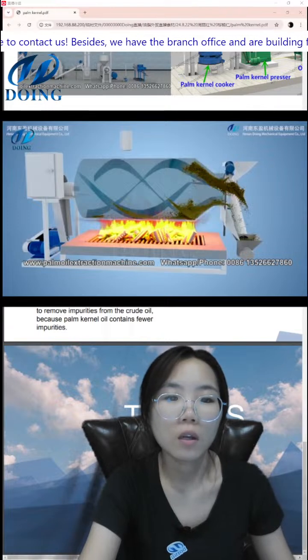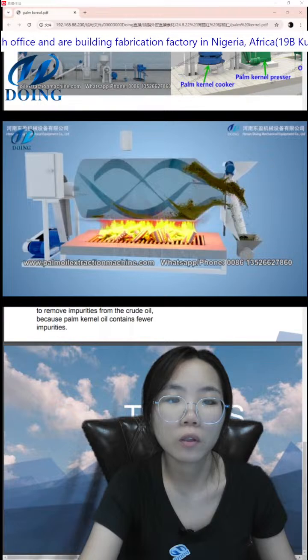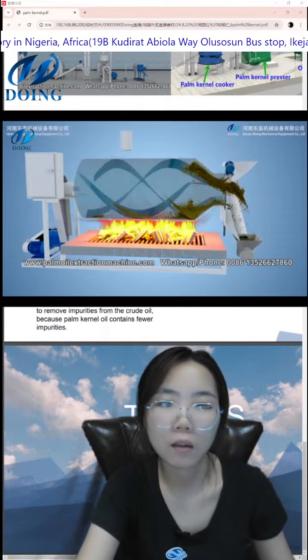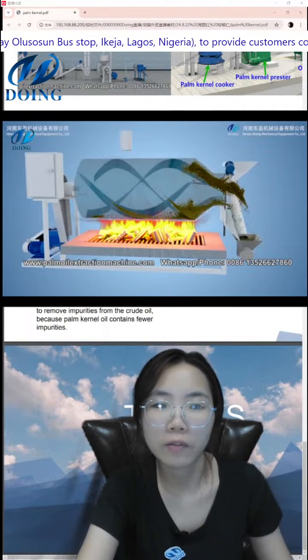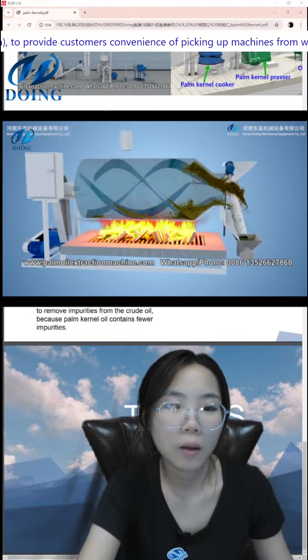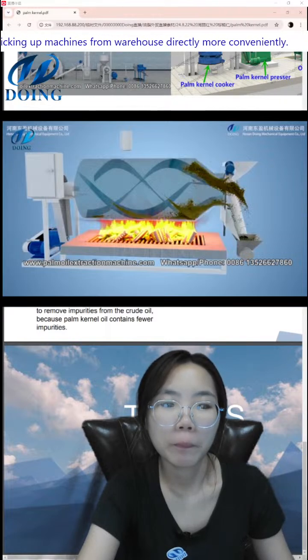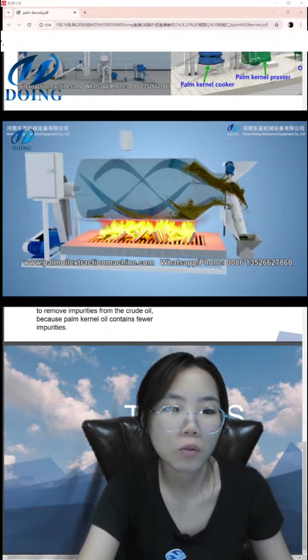For the roaster, the water level before entering the press needs to reach about 4% to achieve the best palm oil yield. And this cooker is the Bellman's cooker. After separation of the kernel and the shell, the shell can be used as fuel.